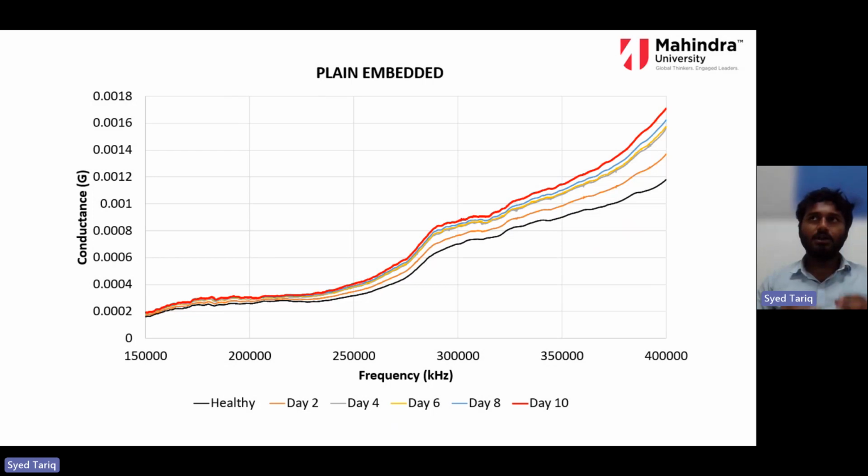to see how the same rebars behave with concrete cover. The time taken for chloride ions to penetrate the concrete and reach the steel surface, the steel bar, is the initiation period. Then when the corrosion happens, that is the propagation period.